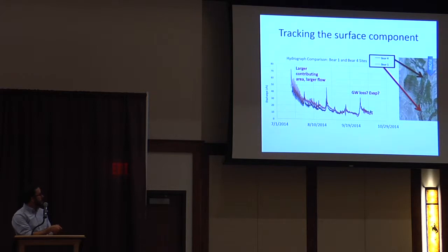The upstream stilling well is called Bear 4, in black and brown, and the downstream one is in red. By recording the level of the stream throughout the season, and then developing rating curves, Scott actually showed a picture of one of those rating curves in the last presentation, where we relate water flow with stream heights, then based on just your stream height measurement, you can gauge how much water is flowing through that cross-section of the stream through time.